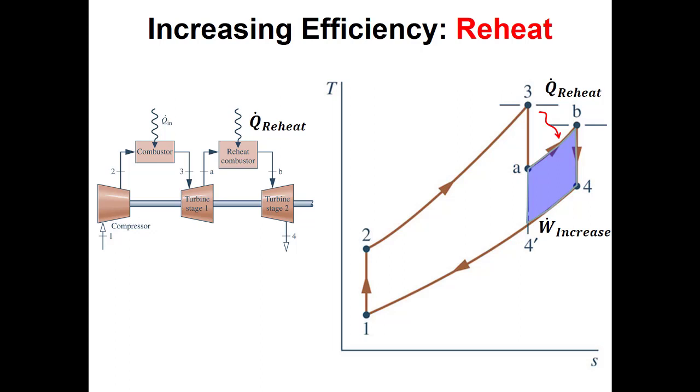And the rate of the increase of the power as we do this reheat is faster than the rate when we're increasing the heat rate in. So this increases our thermal efficiency.